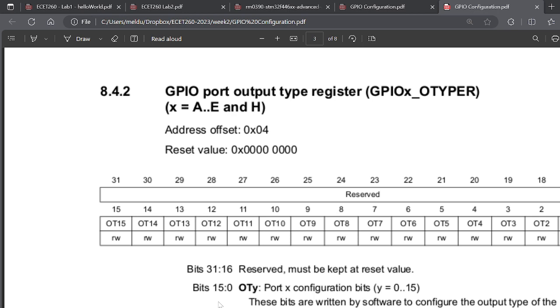And so it's relying on you putting in an external pull-up resistor. Some bus systems, for instance, will have a common pull-up resistor and then use lows to determine something. Or, another way is, as long as the current requirements were okay, you could hook it up to a different voltage level. This is 3.3 volts, and you might have something hooked up to 5 volts.